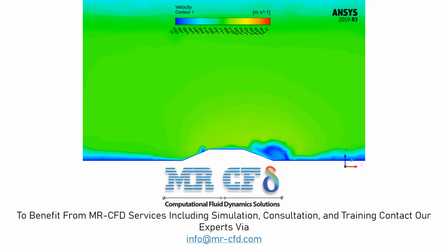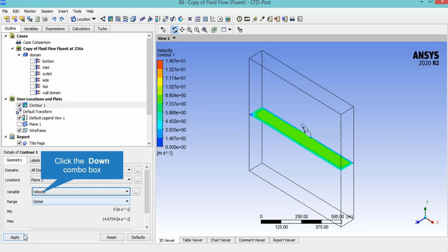In this slide, you can see the velocity distribution over a plane which is placed on the middle section of our computational domain. Also, you can see that behind the mountain there is a region with a decreased velocity indicating that vortices are being generated in that region. You can simply create and extract another contour by just changing the variable section, for example from velocity to temperature, and then by clicking on Apply button.